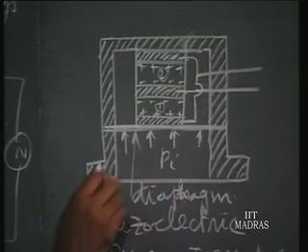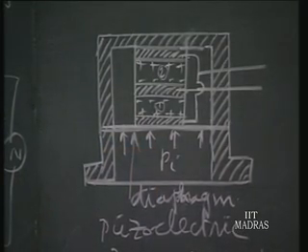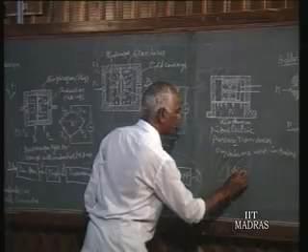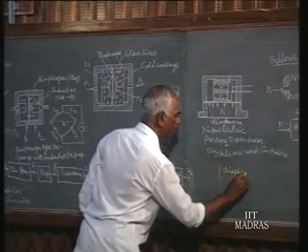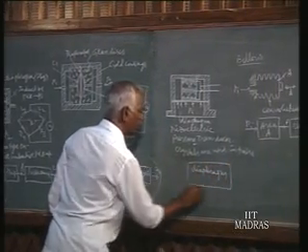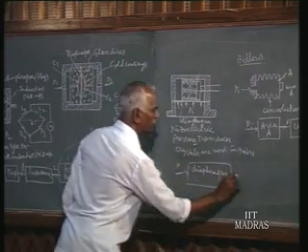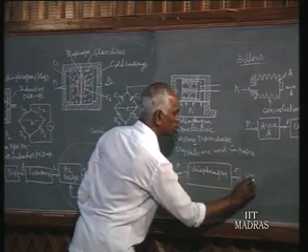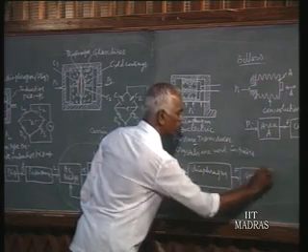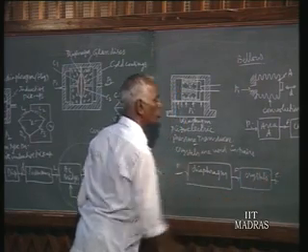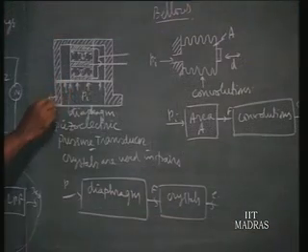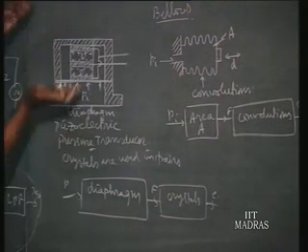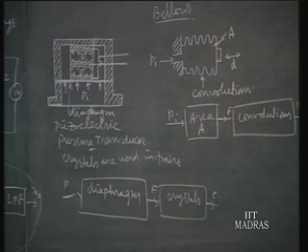Now the pressure is acting here. In the signal flow diagram, this is the diaphragm. So pressure is acting on the diaphragm area, and we get the force. This force is converted by using crystals into charge, or voltage. When the pressure acts, the force compresses the piezoelectric crystals.